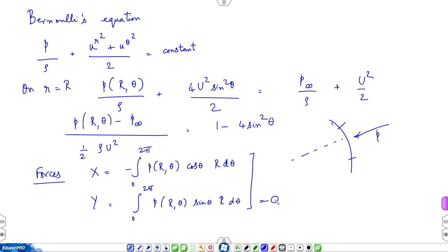Apart from your personal experience, you also have data of C d versus Re. As Re becomes larger and larger, you have a finite value of the drag coefficient. In fact, drag scales with velocity square. So, if velocity is going to infinity, you expect drag to become very, very large. Instead, this result gives you forces equal to 0 and is certainly deserving of an explanation.